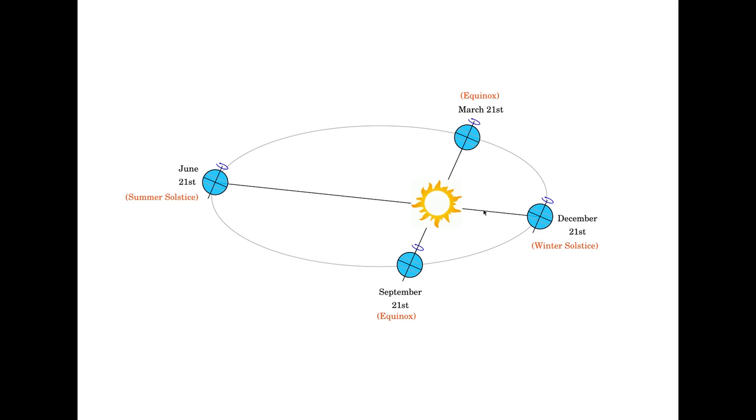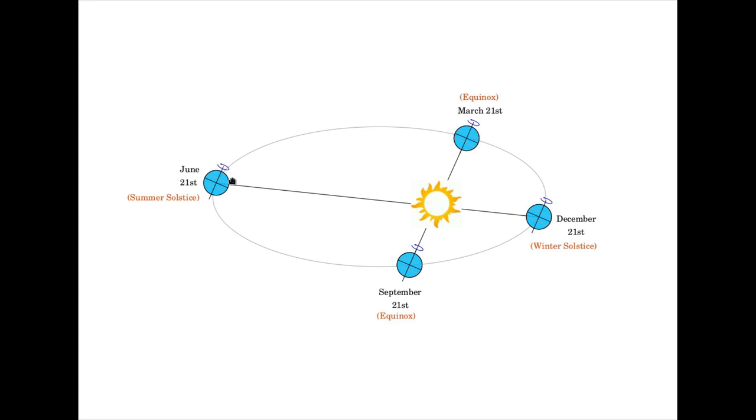And you see that the Sun aligns itself along this line where it touches the latitude Tropic of Capricorn, which is minus 23.5 degrees in the southern hemisphere. So it is summer for the southern hemisphere, and for the northern hemisphere it will be the winter. The line connecting the two solstice points, the summer solstice and the winter solstice, is called the solstice line. And the line connecting the two equinoxes is called the equinox line.